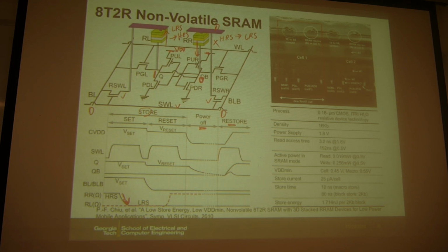And I think the second challenge is endurance. The third one is that the variability and the reliability of the RRAM is still a concern. Unlike the regular RRAM memory array, where you have ECC, error correction, here if the RRAM cell fails, how do you recover? So there are some reliability concerns as well. But it's an interesting application if you can realize this with a certain endurance and reliability. I think it will help with the battery life of your edge devices.